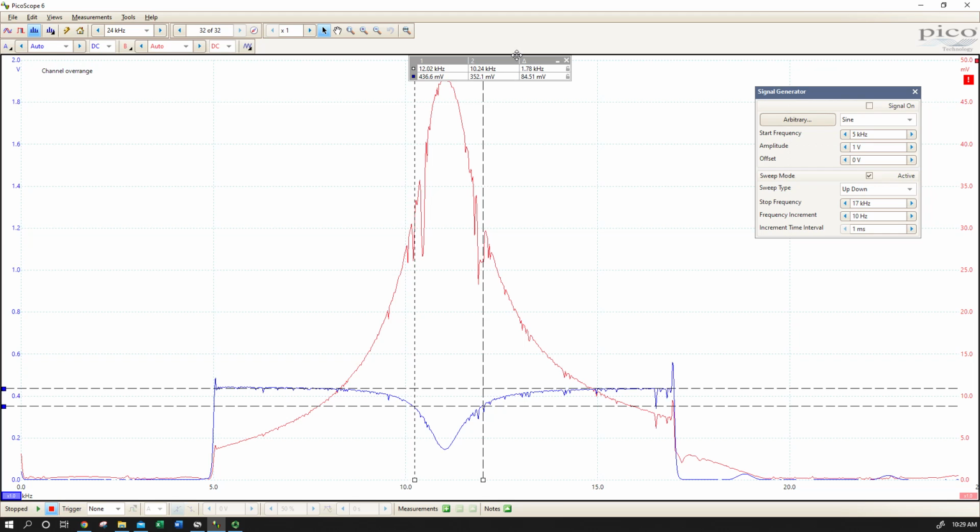So if I were trying to select or exclude frequencies, this circuit would say that anything within this 1.78 kilohertz range of resonance is going to be at half power or better. Or if I'm selecting them through the circuit a different way, they would be at full power and everything else would be at half or less. So that's another way to take a look at that.